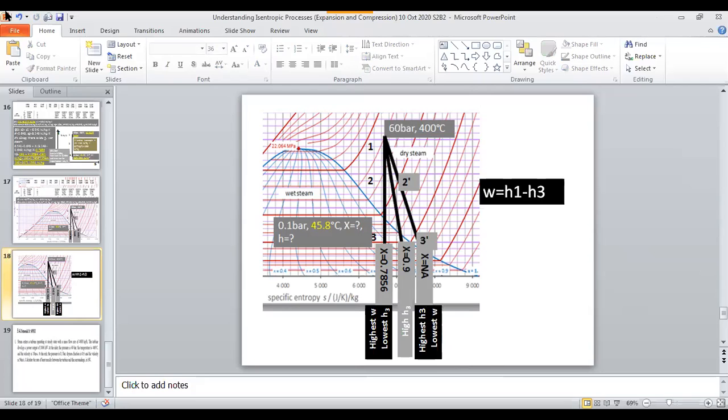Okay, without writing equations. When steam expands isentropically, your entropy remains the same, meaning your loss or unavailability of thermal energy for useful work remains the same. Means the balance is of course delivered as work done. So that is the maximum.